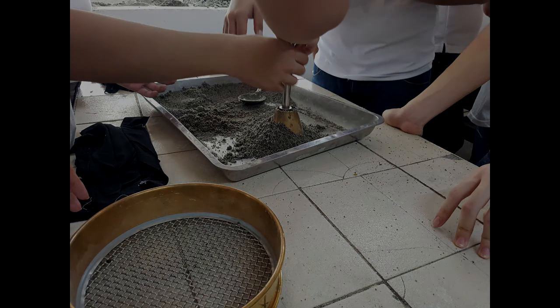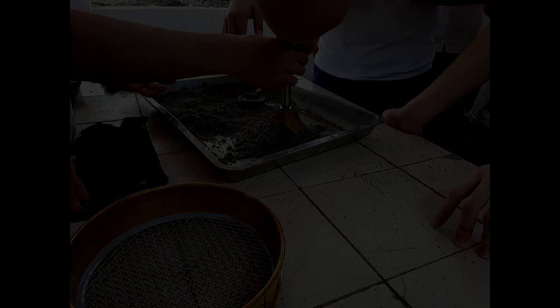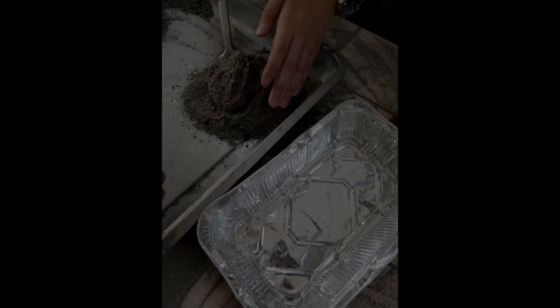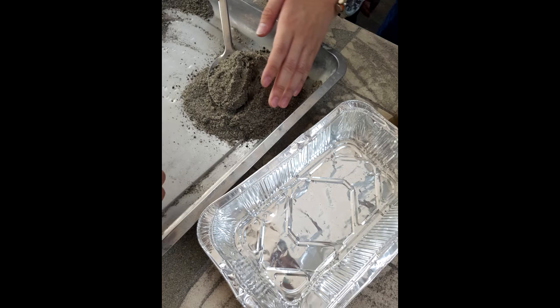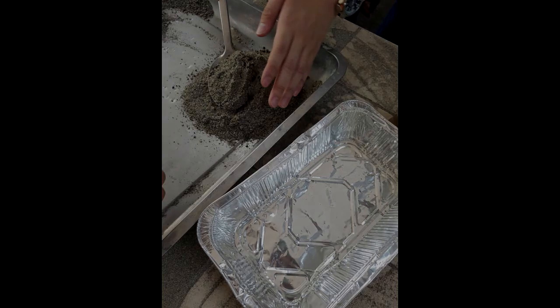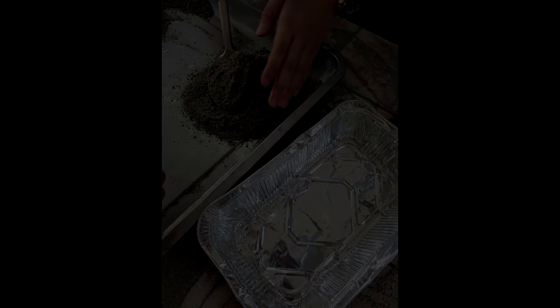The sample that passed the sand cone test will be transferred to a separate pan and weighed. Then, the sample will be transferred slowly to a flask partially filled with water. The flask will be put under a vacuum to release the air particles present in the water-sand mixture. The flask is then weighed, and the sample-water mixture is placed on a separate pan to be dried in the oven. The dry sand is weighed after 24 hours.